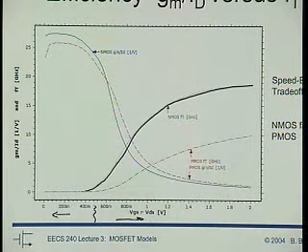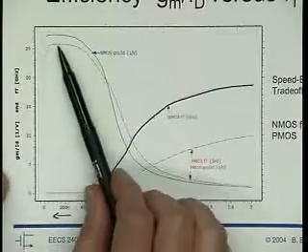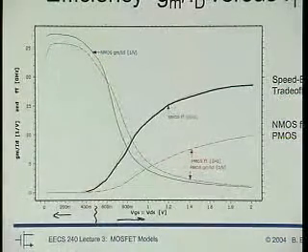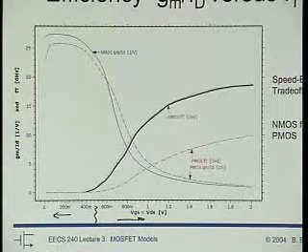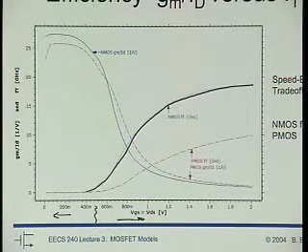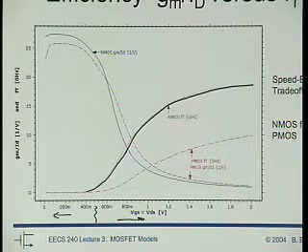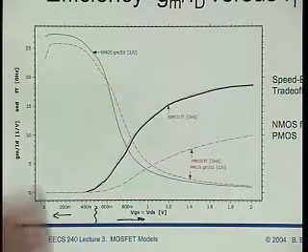There is another interesting thing in this graph, and that is that GM over ID apparently doesn't matter at all whether we have NMOS or PMOS, and it turns out also it doesn't matter whether we have a 1 micron or 0.1 micron process.